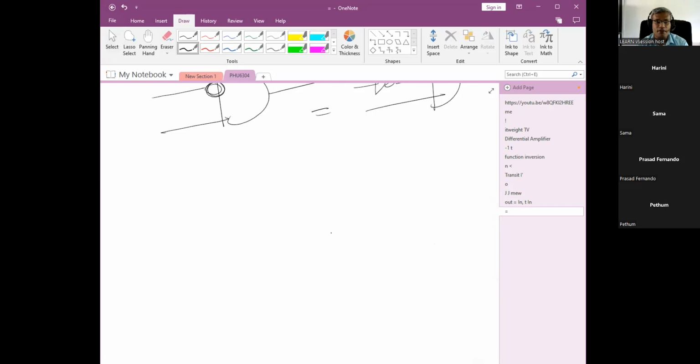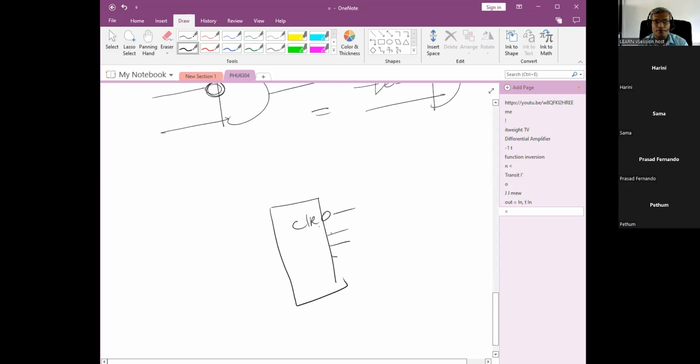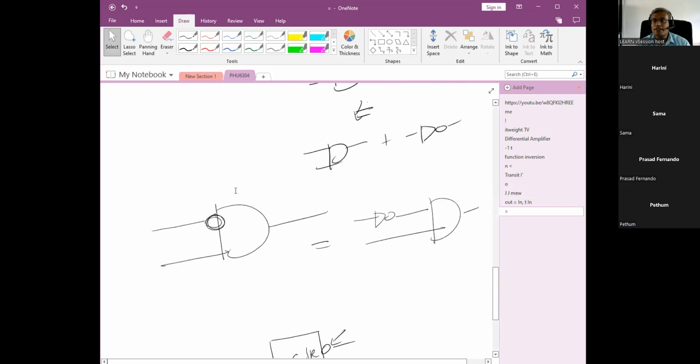Even in ICs, in some IC datasheets, you will see something like this. So you have something like clear, with a dot. There will be another one saying reset. So this again represents there's a NOT gate in it, or it acts inversely to what we usually consider. Usually, when you consider true, you go to a high voltage, 5 volts or plus 12 or something like that. But in this case, to consider it to be true, you have to go to the low voltage because you have a NOT gate. Yeah? So that's something you may find in other circuit diagrams.